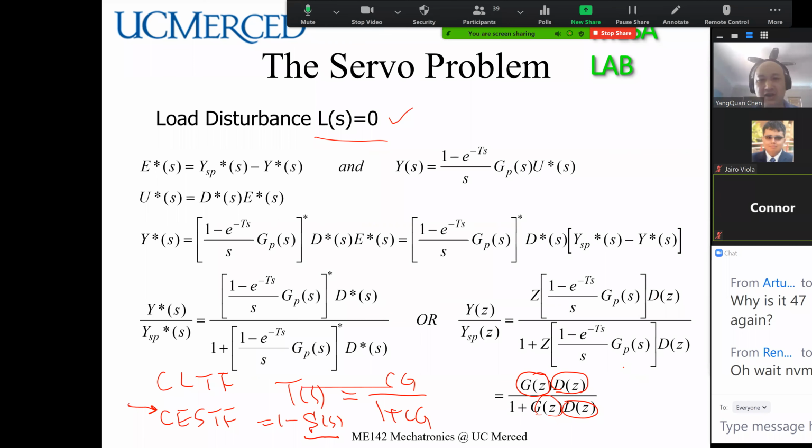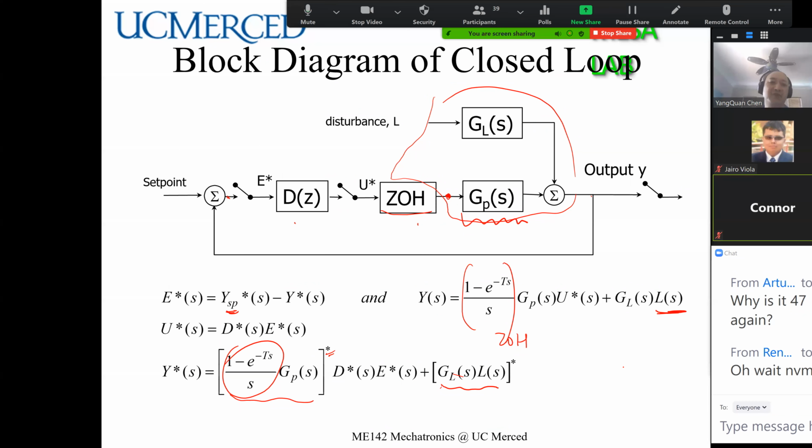So we talked about control tasks previously. There are two types. One is where the set point is a constant. This is called a regulator. Like your room temperature, you want to maintain a certain temperature. So that reference is constant, it is a regulator. But what if your reference is a curve? Then you need to track it. So this is a tracking controller.